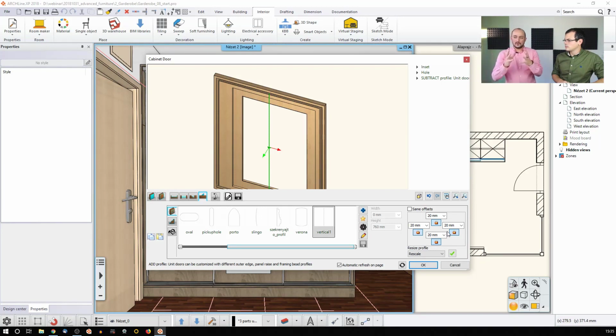If you work with a section, an open profile like this is a single bar. The software understands these because they are both locked, and you can see these tiny padlock icons. They are all locked. So this way you tell the software, okay, keep 20 here, keep 20 here, keep 20 here, and keep 20 here as well. How does it know? It can only be solved if it is pulling with the same power the same way, so it's like a ratio. It's 50-50 actually. If I disable this option, I can tell the software, don't mind what happens here, just keep it locked here. I can do the same the other way around.